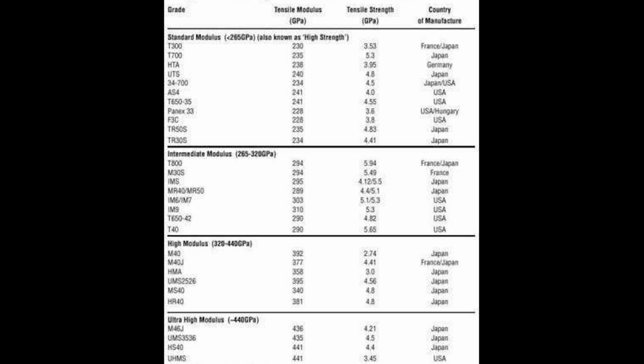Definitely better. But the only downside with the intermediate modulus fiber is the cost. Basically, it's both stronger, it is stiffer, and it's even better for impact than the high strength fibers. So the only downside is that it's twice as expensive for the fiber itself.